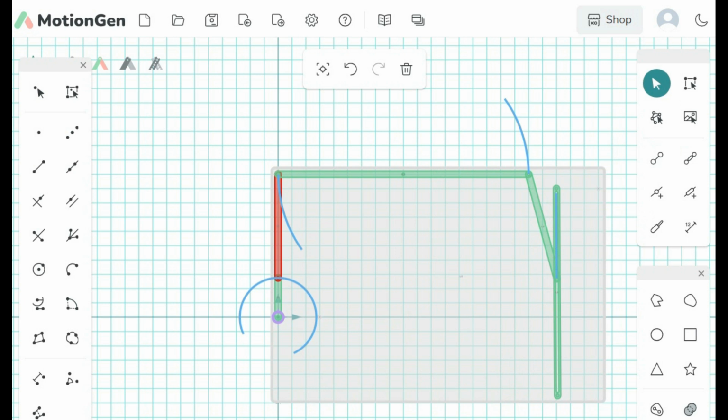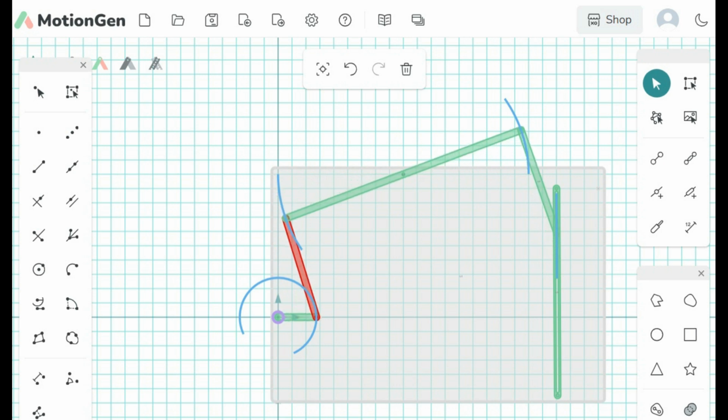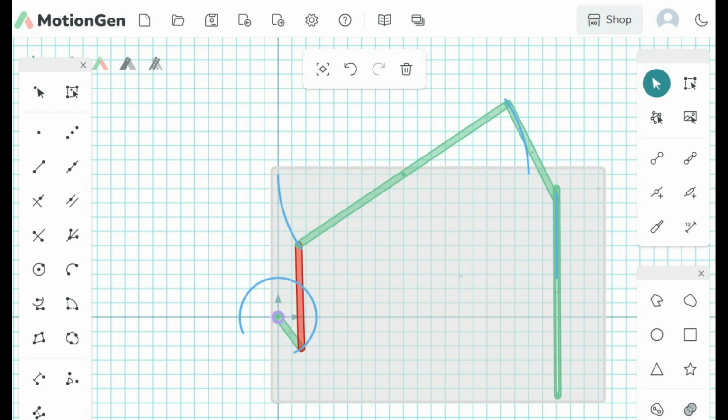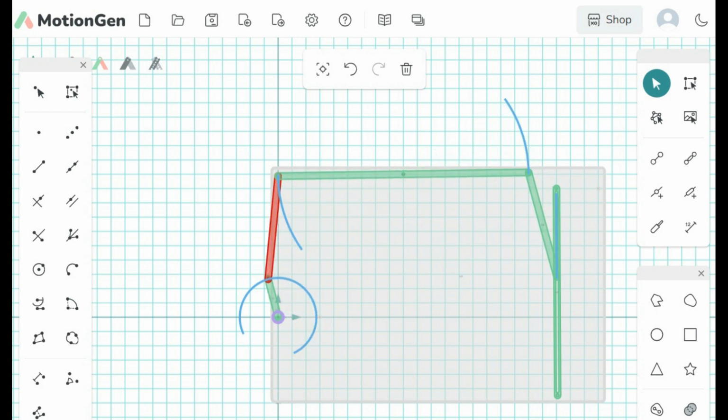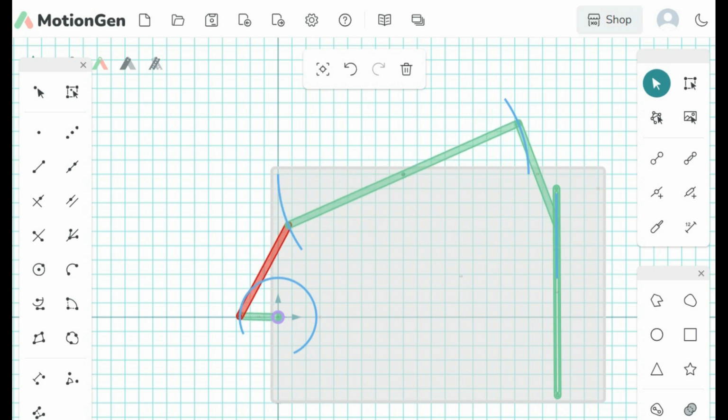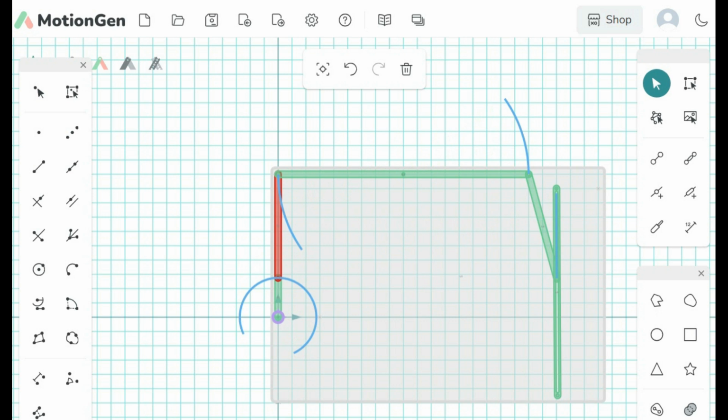However, notice that our circle down here on the crank doesn't go all the way around, which means we're going to hit. So let's just run it and verify what's going on. So you see the piston go up, but it hits the end up there, which causes the program to reverse directions. So let's stop. We need to bring that on up a little more. Take it up to here.